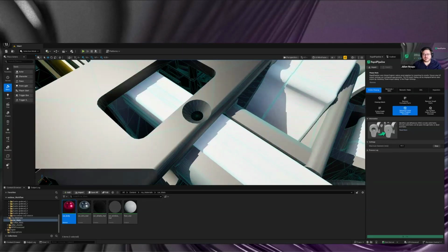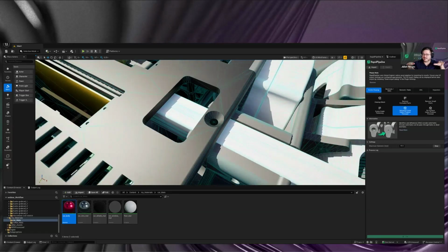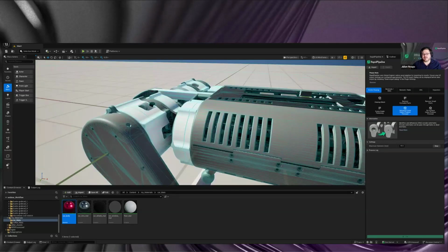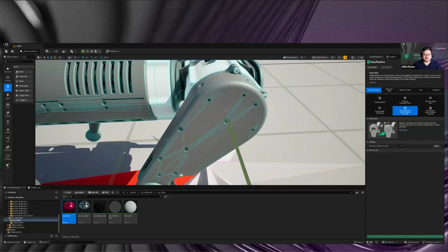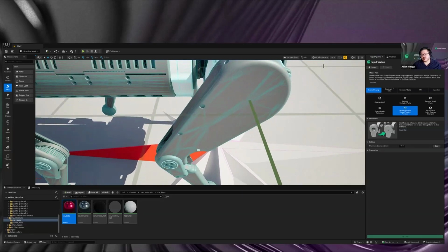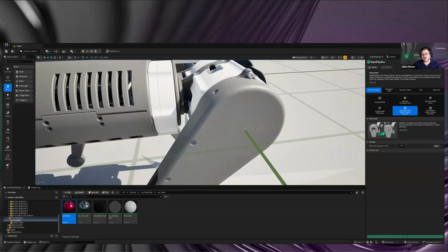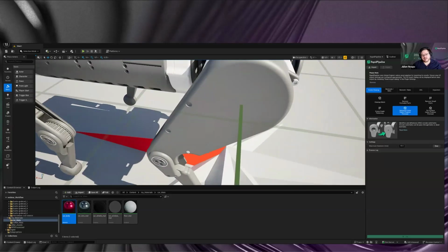As you can see, this hole penetrates a little bit into this bevel, and that makes it not perfectly circular on a flat surface. That's the limitation we have right now. If you go to a different side of the model, select the side of the arm and run the operation again, only the holes sitting directly on top of the flat surface are closed. The ones sitting on a curved surface or barely on the edge of the bevel will not be closed at the moment.